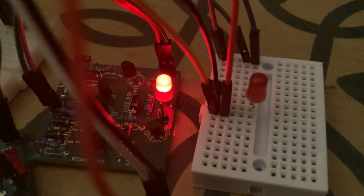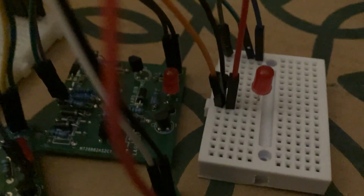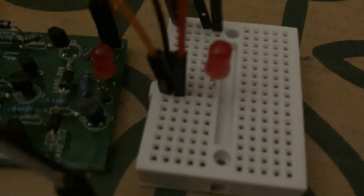Okay, let me illustrate it better. Okay. You can see, this is carry. No, this one's carry and this one's out. Which basically means this one is worth 1 and this one is worth 2. So, 0 plus 0 plus 0 is 0. 0 plus 1 plus 0 plus 0 is 1. But 1 plus 1 plus 0 shouldn't equal 0. But if I do 3 again, then 1. Which basically means this AND is not ANDing when it should.